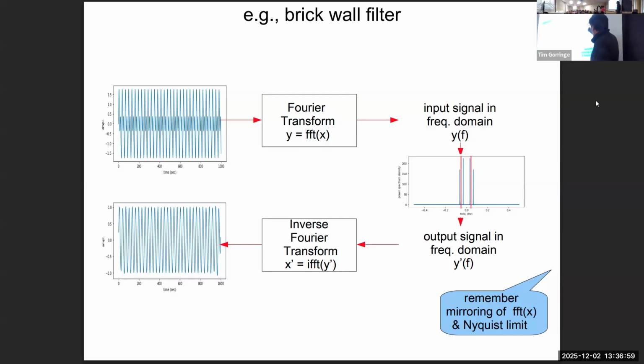I'm going to apply a mask in the frequency domain, a mask in which I keep the frequencies that are lower than these red lines and reject the frequencies that are above these red lines. So just like multiplying this array by a mask that is either zeros or ones, it's ones below a cutoff frequency, it's zeros above the cutoff frequency. That's going to be my new filter, my frequency domain low pass filter.